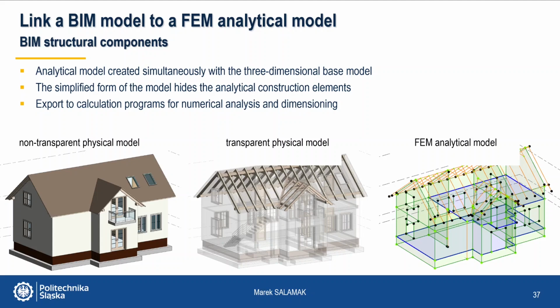For example, an architect or installation engineers, facility engineers, cannot see them because they do not need them. The analytical model can be exported to calculation programs, analyzing programs, where static or dynamic analysis and dimensioning of structural elements and connections details are performed.